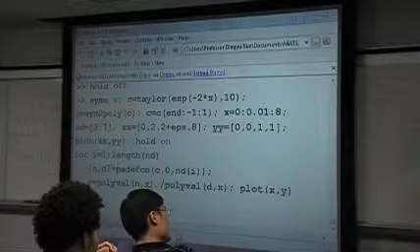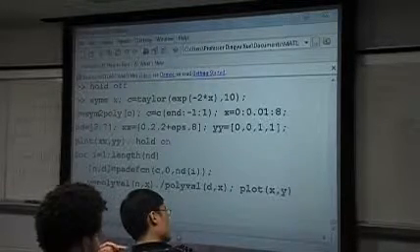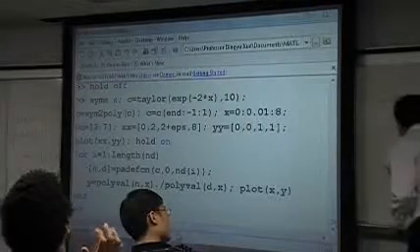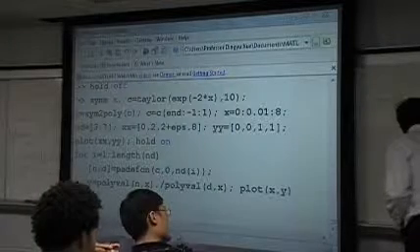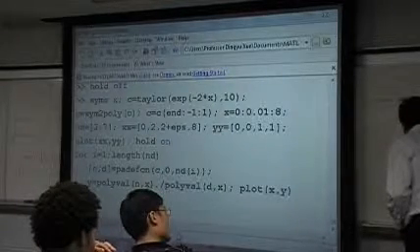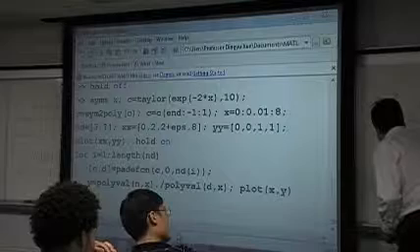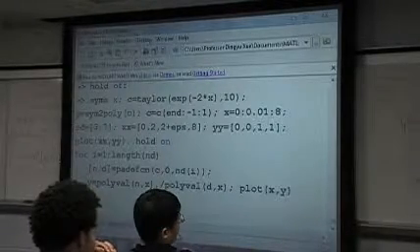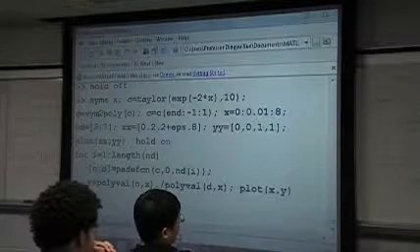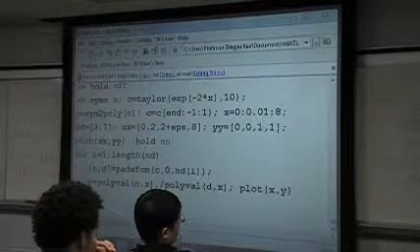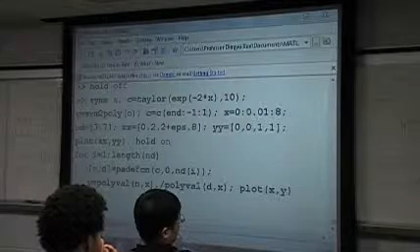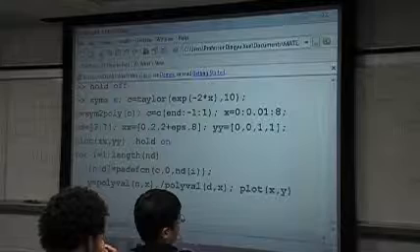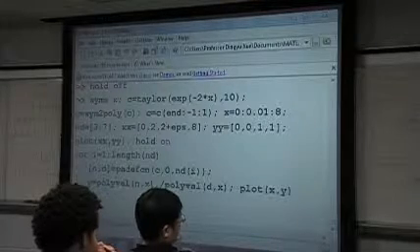So sometimes you have to use Padé approximation in control system analysis. The equivalent transfer function representation should be something like this. And you can leave the delay out of the loop. Normally, if you select the Padé approximation of degree 3 by 3, you get quite a good approximation to the original problem.